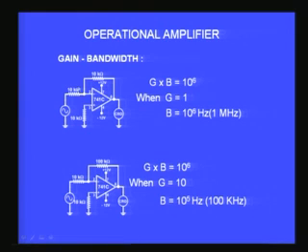You have RF and RI, both are 10 kilo ohms, and pin number 3 is grounded. There is no input with a 10K to compensate for the input bias current variations, about which we have already seen. The output is seen on an oscilloscope, and the input is from a signal source, a sine wave oscillator, whose frequency can be varied up to several megahertz.